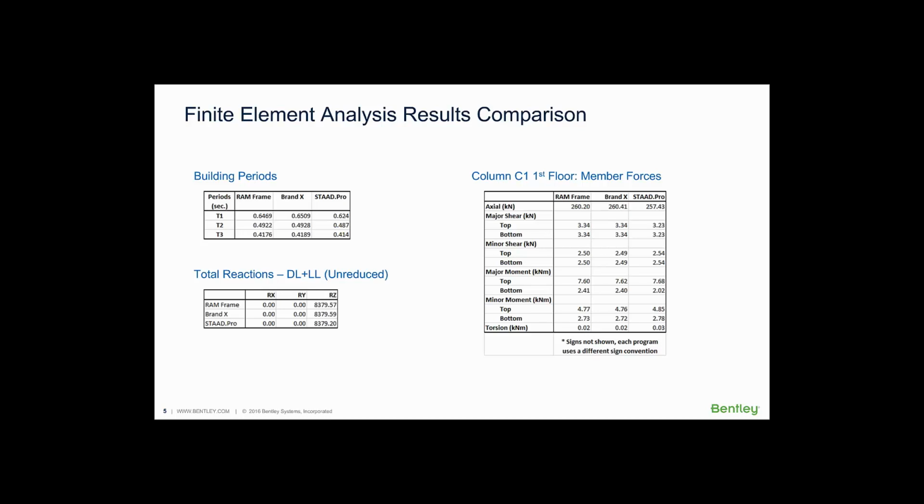Now, where it does get different is the implementation of special analysis options, such as, how does the program handle p-delta analysis, for example? How does it handle live load reduction? How does it handle response spectra analysis? So that's where you'll begin to see differences in results, but more particularly, that's where you need to really make sure you understand what it is that you need to input and how you need to specify those, because that's where the criteria and the options that you're presented with become important.